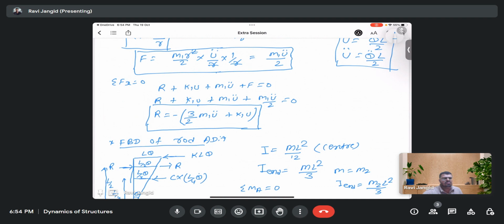Actually, I have only one doubt. For dynamic analysis, there is a response spectrum method and time history, right? So what is the difference between these two? In response spectra, we are considering the particular earthquake and we are considering the peak responses with respect to that time period. So what are we doing in time history?